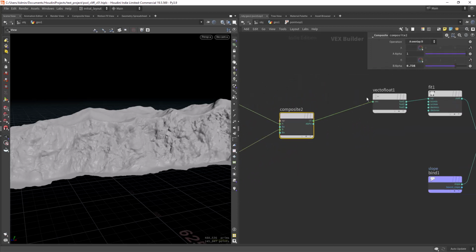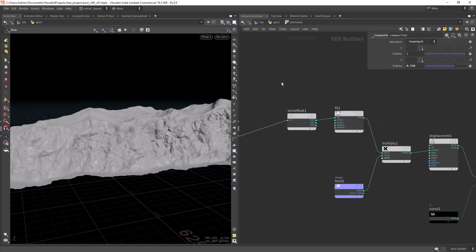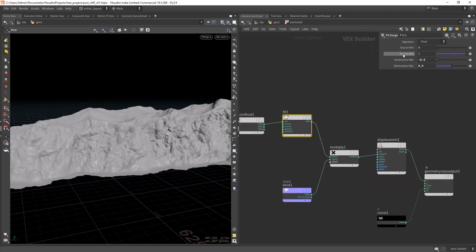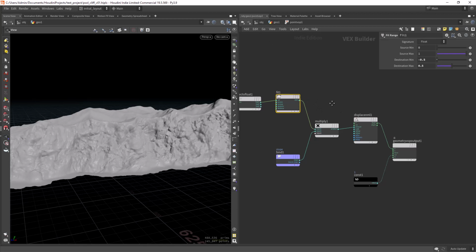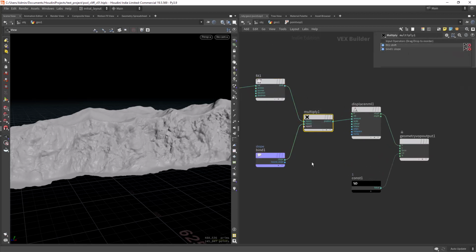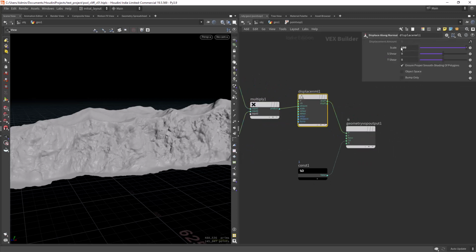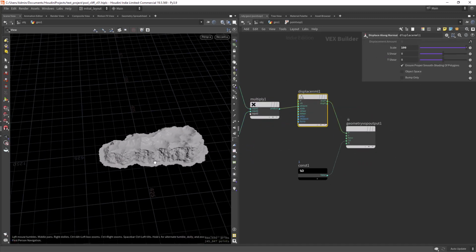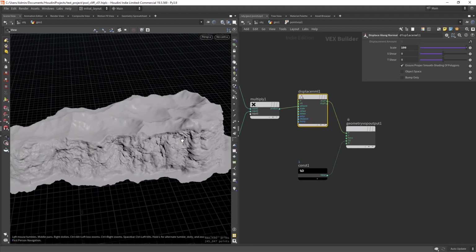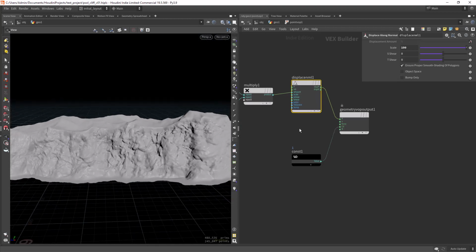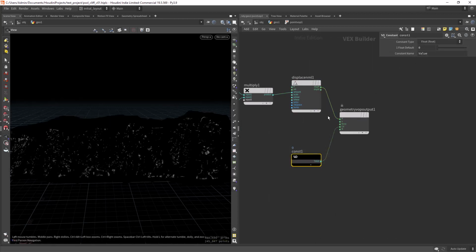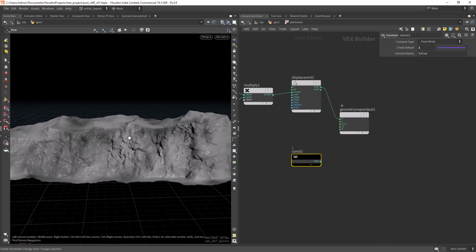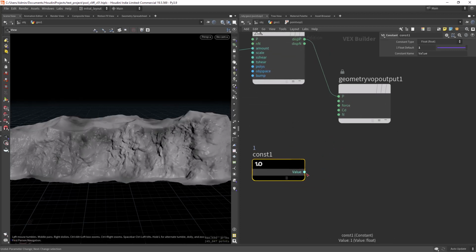As you can see, I'm reducing the alpha of the third texture, converting it to a float, fitting the range between -0.5 and 0.5, because the zero value of the Megascans textures is 0.5, multiplying by the slope, and displacing quite a bit, because this is a large model, as you can see. So we need to displace it quite a bit, and just adding a constant to the color, otherwise we have the triplanar color.